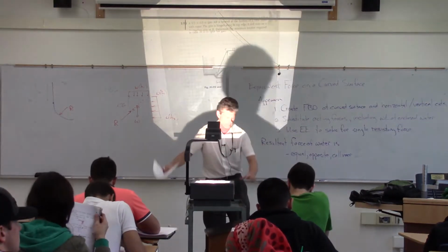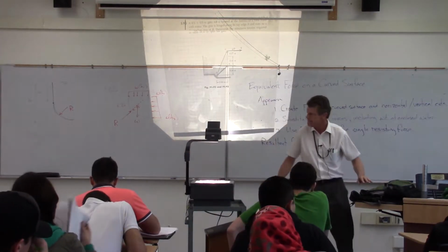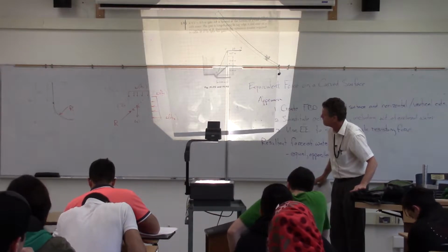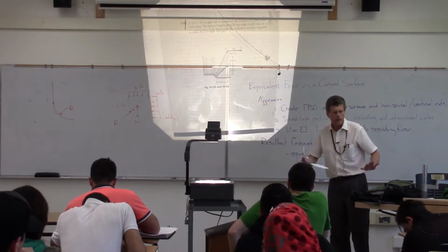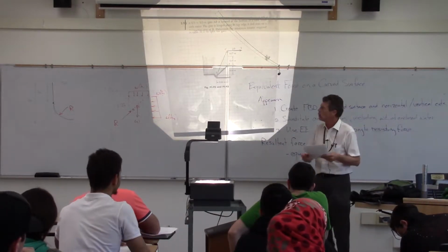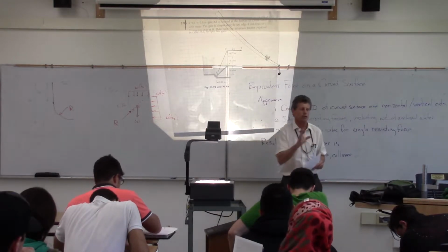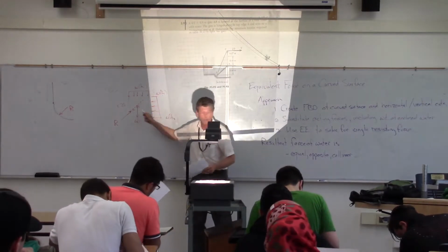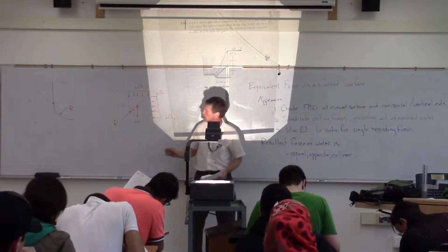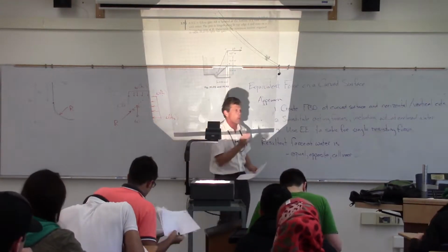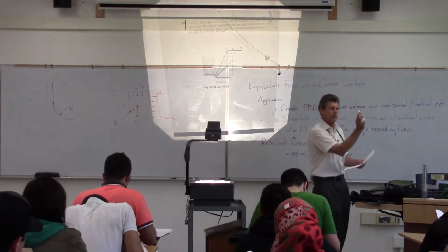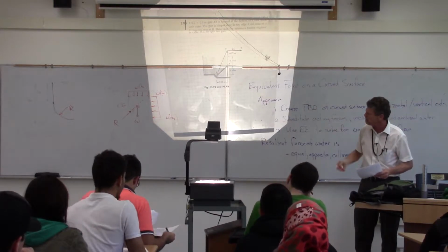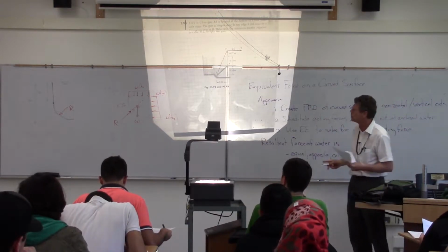So that resultant there, is that going through that line of action? Is that going through like the radius, or is that going through that center of gravity? It may not. It will find its own location, so there's no rule that it has to go. The only thing that goes through the center of gravity will be the weight of the water. That's the only thing we need that for, just to figure out where that weight component's going. But when we find that resultant force or the resisting force, that single resisting force, it could be basically anywhere. Good question, though.